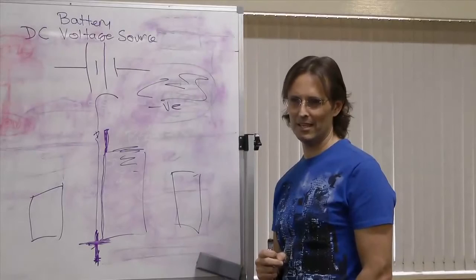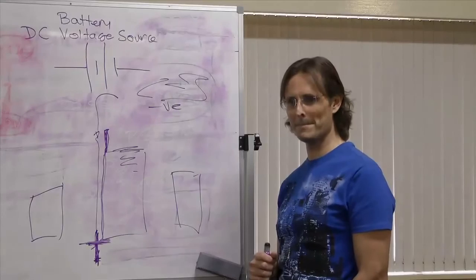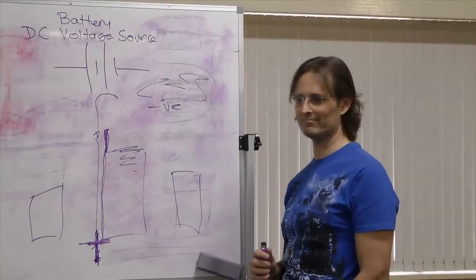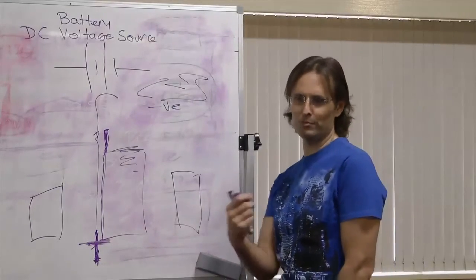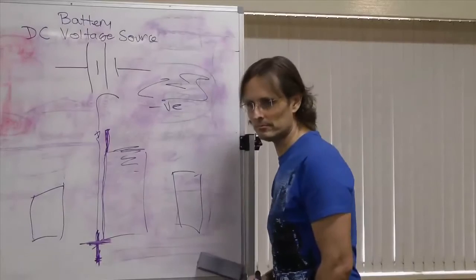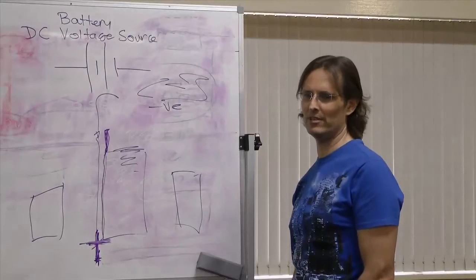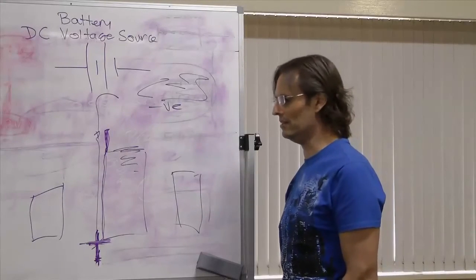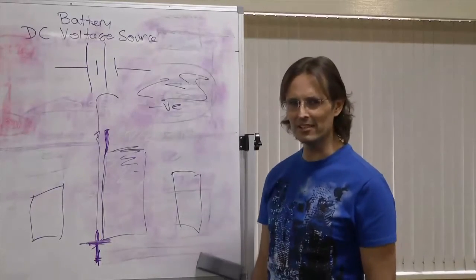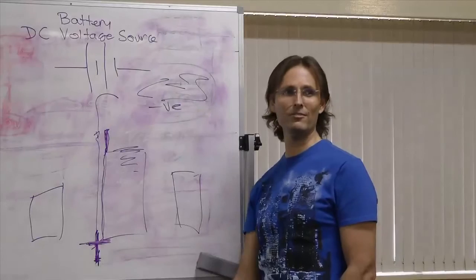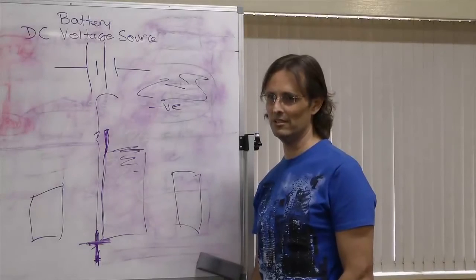So when you have your appliances and you plug it into the power point, like how the bottom one is called earth, that somehow is connecting to this system in the house? That's connecting to earth. So the wiring would somehow connect to this thing in the ground of your house? Yes, it should be connected to that in the ground of your house. And then you can get what's called an earth leakage device, and that tells you when something's leaking current to earth, and that can switch off the power of your house. So that's a very safe way of managing alternating current.